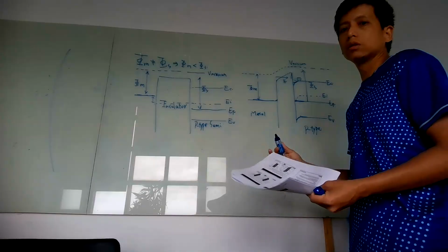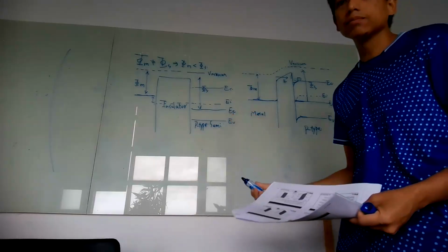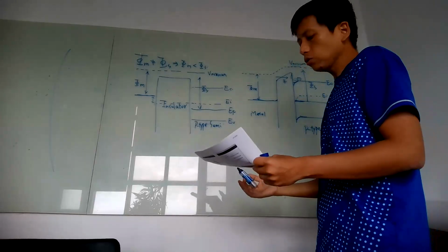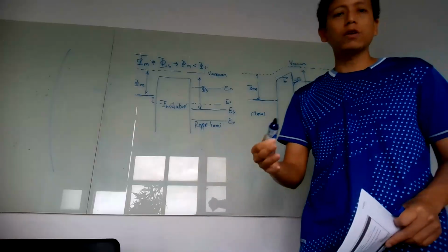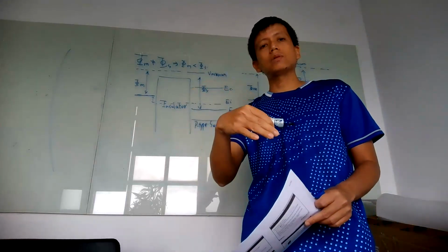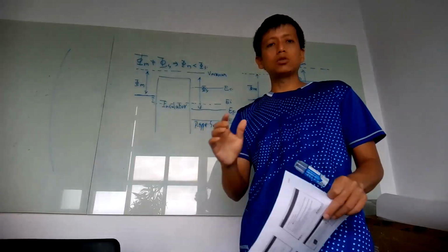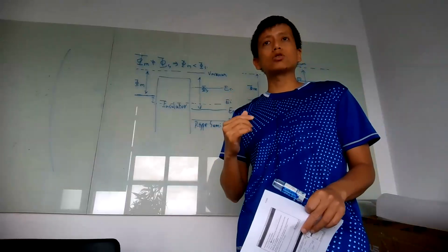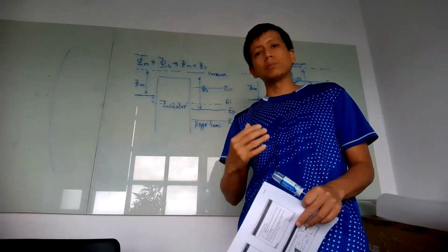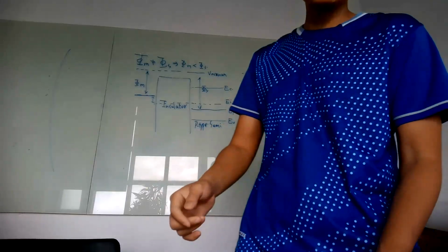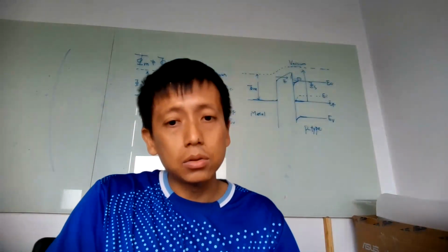But the next thing is, if you want to talk about the band diagram, or talk about the previous slide, what should it look like? You need to apply a voltage in order to discuss further. For instance, we previously mentioned what the depletion position is and what the accumulation position is. For that circumstance, we had better start with the flat band in order to judge whether this structure is in accumulation, depletion, or inversion. Okay, so let's do these things. I want to first start the